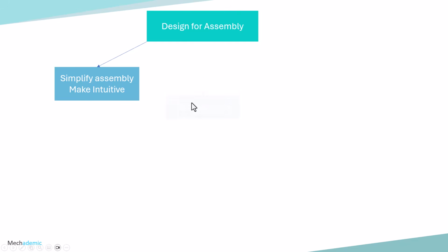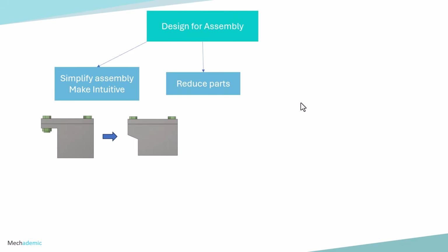The next important principle is reducing parts wherever possible. Now, when we are designing a concept, if we find that there are certain parts which can be reduced, say 3 components which can be made into one, as in the earlier example, or 2 components into one, or whatever that may be, we should do that and reduce the number of parts possible. That increases the ease of assembly and also reduces the cost of assembly. Here are some examples which show these 2 principles at play.